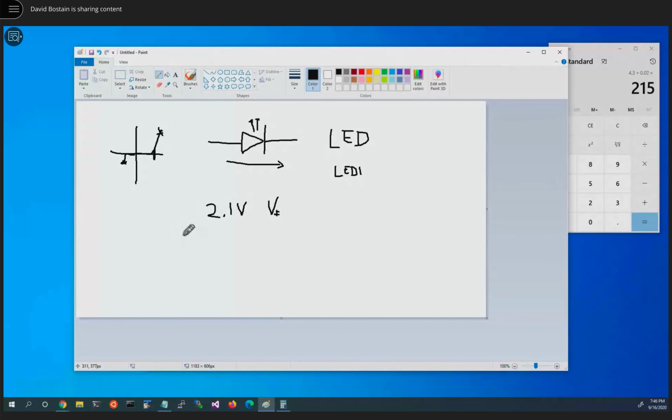We also are going to go to the spec sheet, and if I don't tell you otherwise, your diode needs to be using 15 milliamps of current to be seen and should not have more than 25 milliamps passing through it to keep from burning up. So it has to be in a range: 15 is safe, 25 is safe, above and below that is not. So if I were going to design for this, I would pick some other value. I wouldn't pick 15, I wouldn't pick 25.